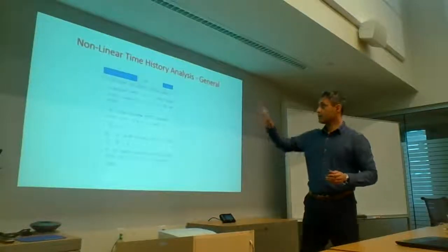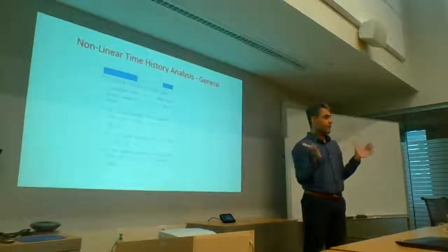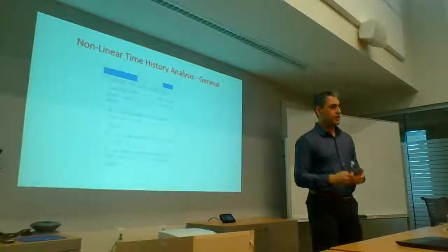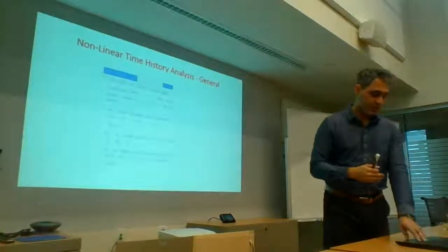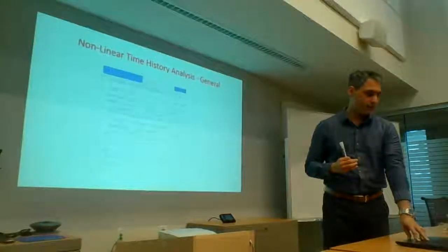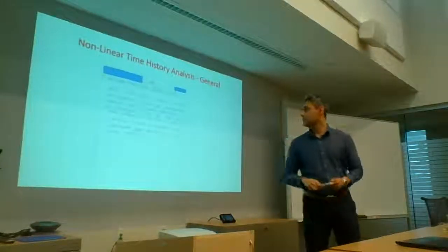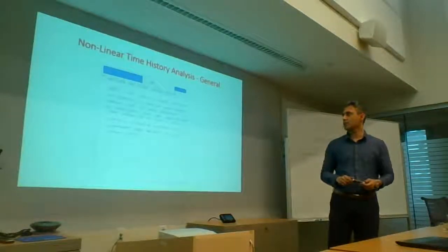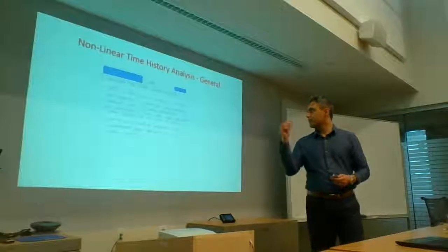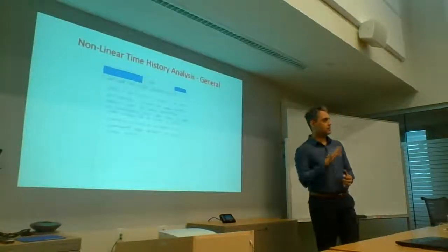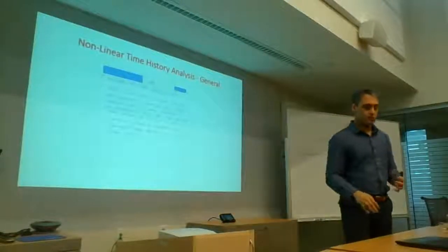Okay, so unconditional stability is that you will have a bounded solution no matter what the time step is. Whereas conditional stability, you have to account for the time step. It has to be small enough. But as I said, the stability criteria are not too restrictive from ground response analysis because the values are already given at 0.01, 0.005 seconds. So those are already very small intervals.